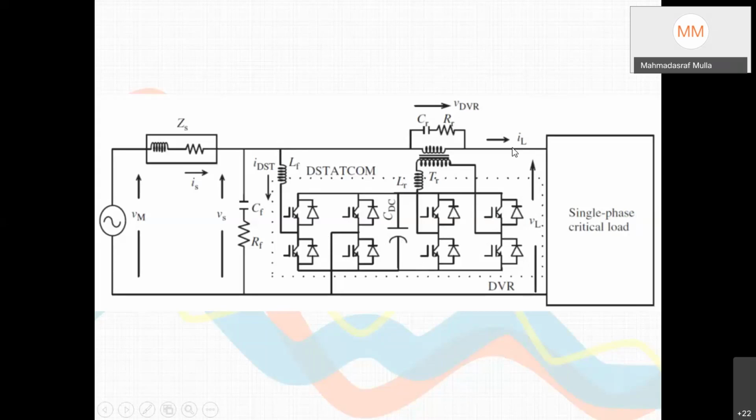So you can further increase the value of load voltage above what can be compensated through reactive power, by injecting some active power. So you can draw some active current, and active current is in phase with voltage. So you can draw some in-phase current also. The total current we will be drawing here is active plus reactive. So no longer will there be a 90-degree angle between voltage and current here as well as here. Okay. But why do we go for UPFC?